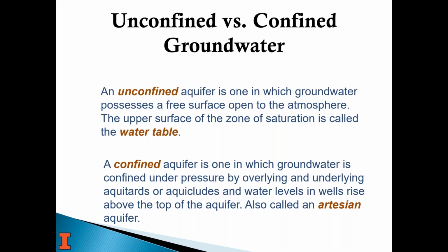And above the water table, it's not saturated, okay? Whereas in a confined aquifer, the entire aquifer is full of water. And it's such that it's even under pressure, because somewhere else further to the left, right, front, or back of where you are, the aquifer is either higher up in elevation, or there's water coming in from recharge that's pushing on the aquifer. If you think about a bathtub, it wants to be flat.